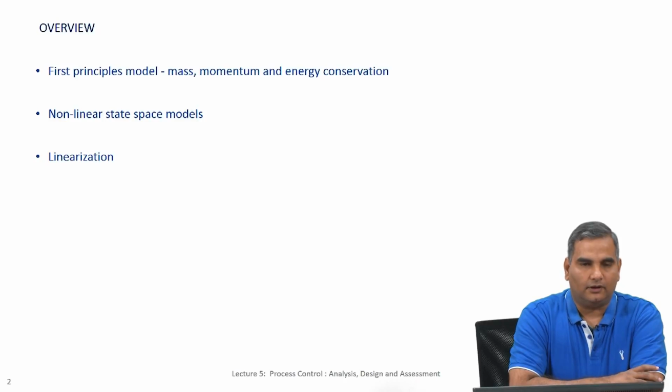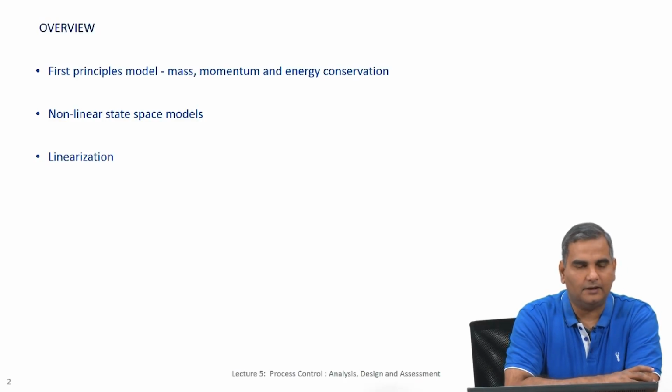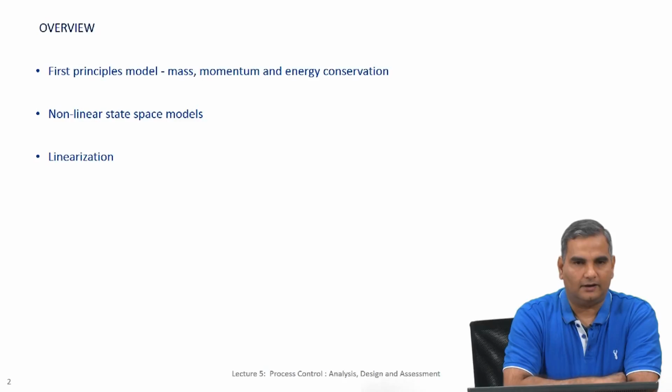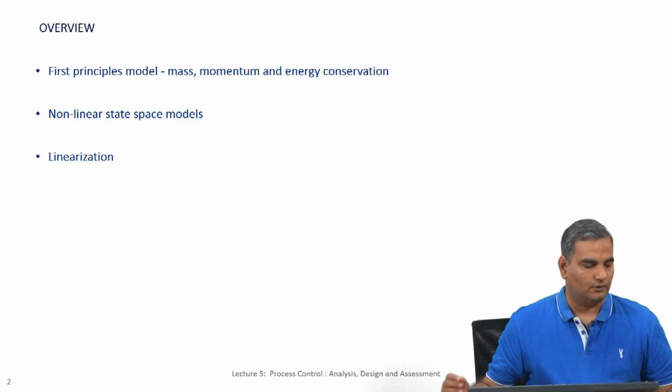And as I have been talking before, we typically assume in the undergrad process control that we teach, the underlying processes are linear. However, most real engineering processes are nonlinear, particularly chemical engineering processes. So, to be able to apply many of the techniques that we describe in this course, you need to linearize the model so that we get it into the standard linear form. So, I will teach how we do this also.